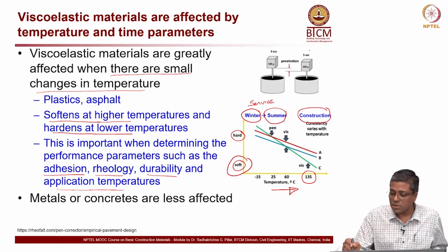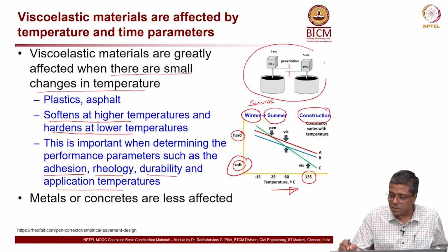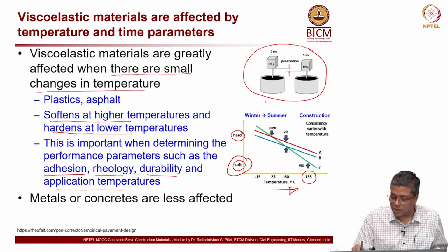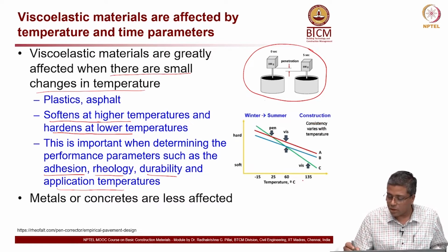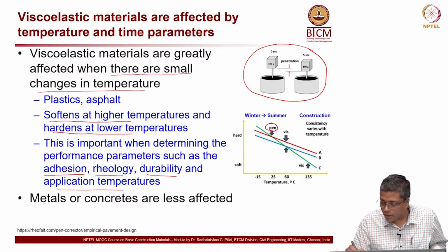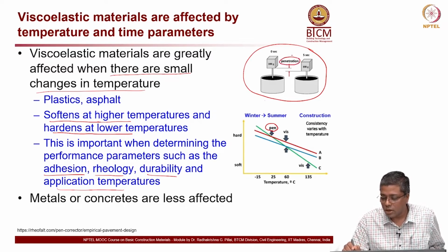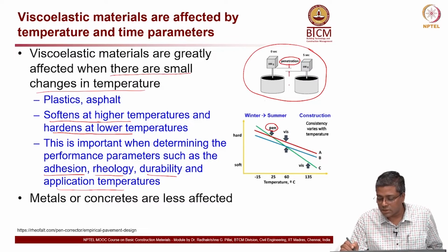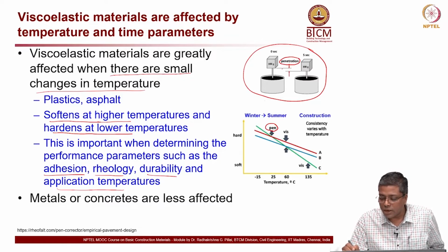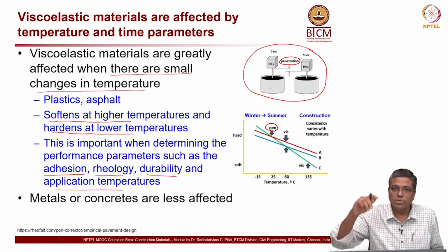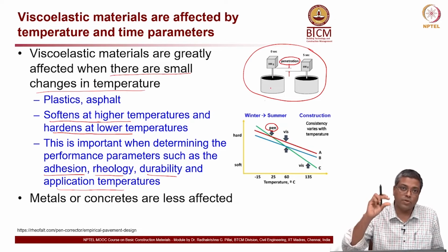Okay. So, the picture on the top over here is basically how these typical asphalt materials are tested. This PEN here is the penetration. This is a test which we do in asphalt. You will do this test again in some other class, but for penetration, you basically take a needle and put it through the asphalt and see how much is the depth of that penetration.